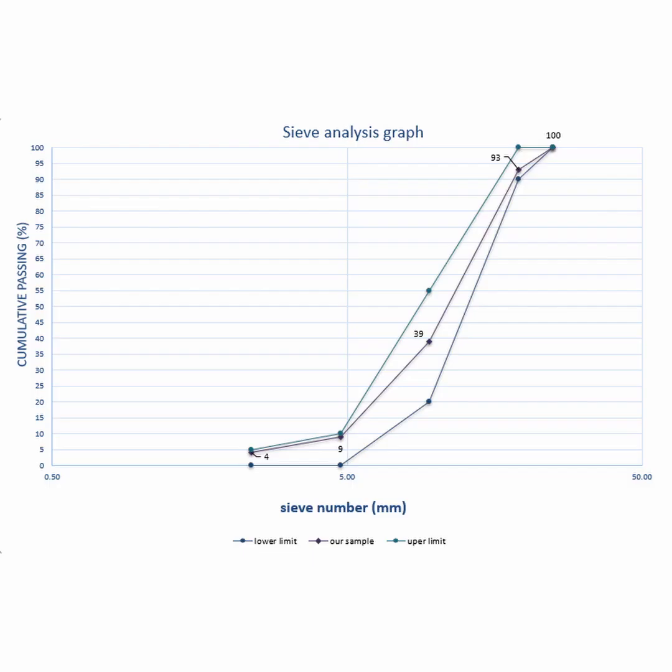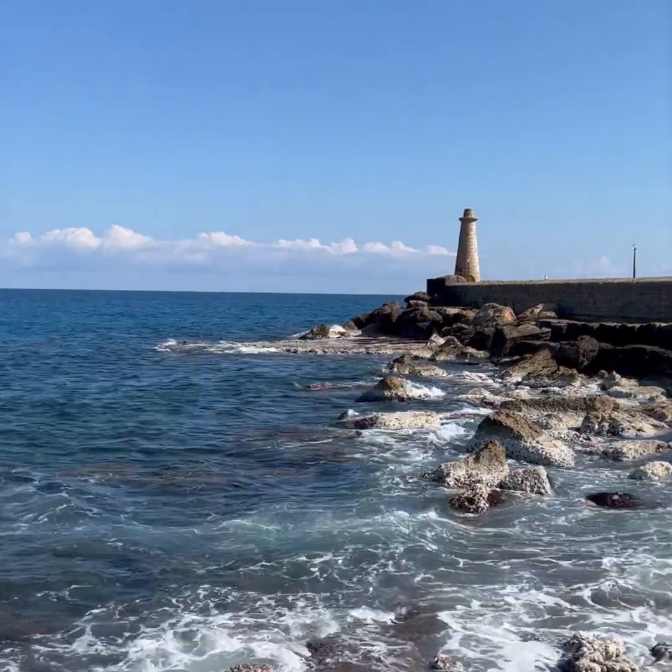At the end of the test, I drew a sieve analysis curve for our results and included the upper and lower limits from the ASTM C33 standard to visually compare and confirm that our aggregate mix design met the grading requirements. Great! That's the end of today's video.